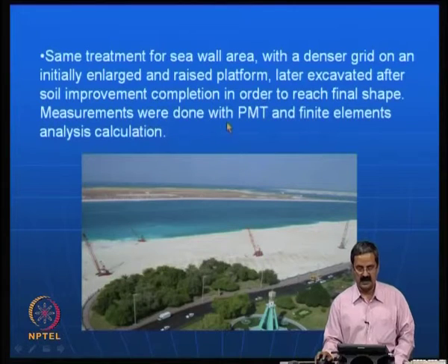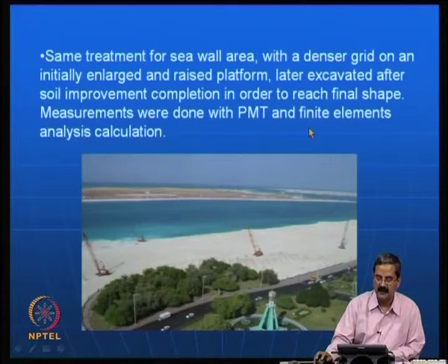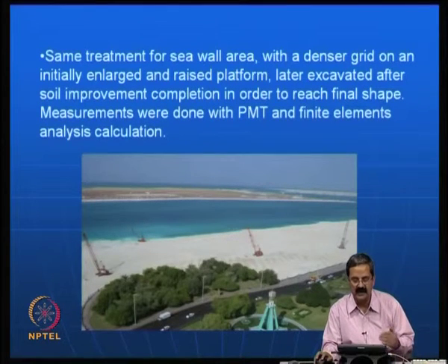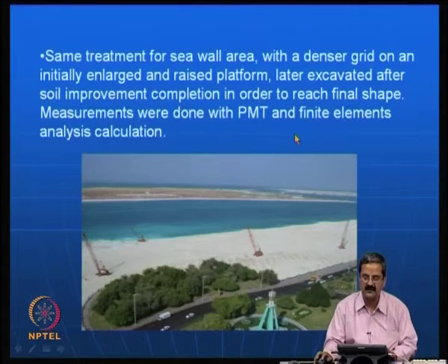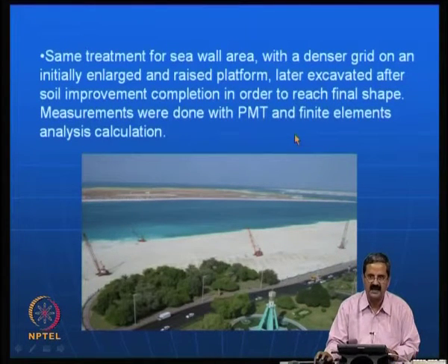So, measurements were done with pressure meter test and finite element calculations. In fact, one should verify some of these calculations and prove that, because you need parameters like Young's modulus, Poisson's ratio and other model parameters for finite elements, one should use sophisticated testing. That is the reason, in fact, pressure meter test was used.